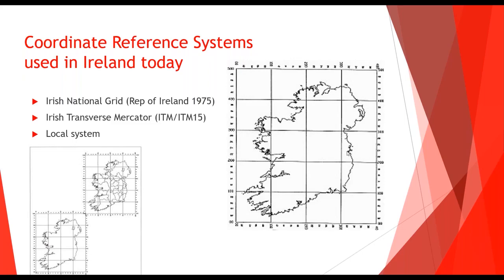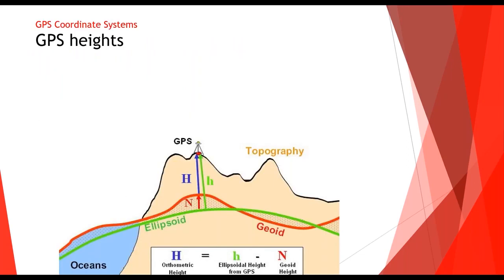Commonly, if it's using local systems, the digits will actually be a lot lower. So you won't have 6 digits, they might have 3 or 4, because generally they'd start the origin point at 100, 100, 100, or 500, 500, 500, or something like that that makes sense to them, and it's easily computable then to do offsets. Okay, so moving on from this, the coordinate reference system is made up of grids, which specify where we are located in Ireland relative to the easting and northing. So that positions us a location.